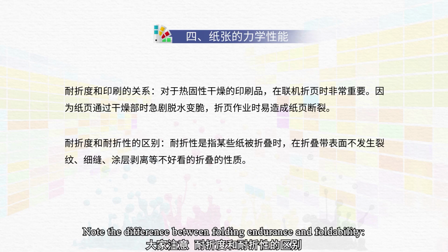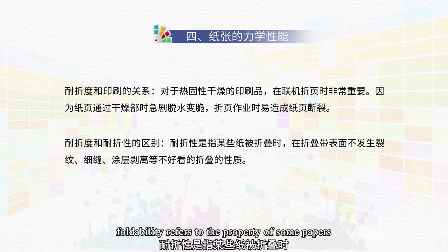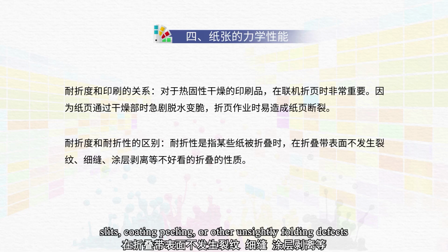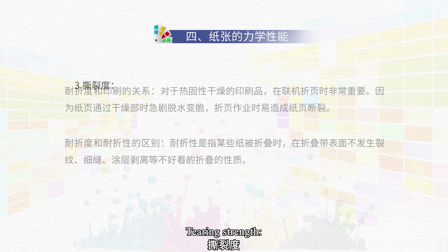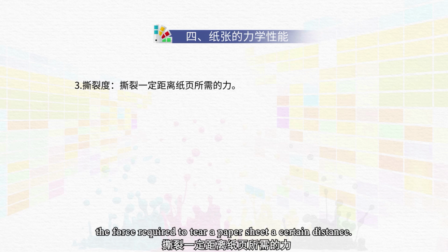Note the difference between folding endurance and foldability. Foldability refers to the property of some papers that do not develop cracks, slits, coating peeling, or other unsightly folding defects on the folding belt surface when folded. Tearing strength, the force required to tear a paper sheet a certain distance.